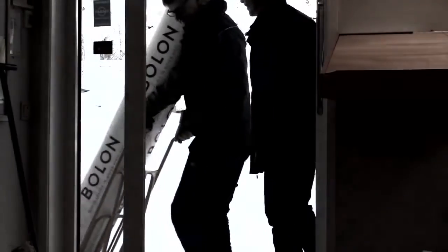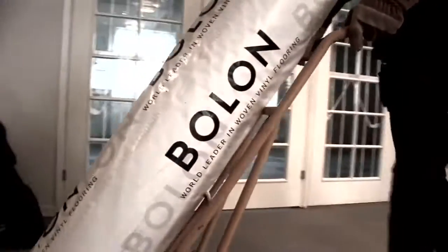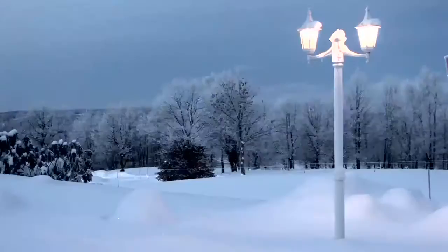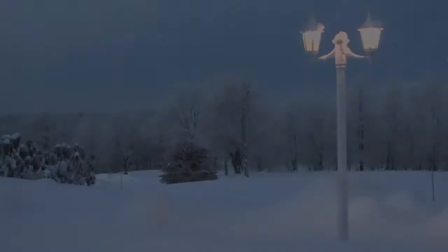To obtain the maximum life of the flooring in service, it's important that there is an effective entrance system in place. The risk of stains and damage to the new flooring can be reduced by ensuring the walls and ceilings are completed before the flooring is installed. The material must have adjusted to room temperature, at least 18 degrees Celsius, before installation. It may be necessary to bring the material in the day prior to the installation and leave it overnight.